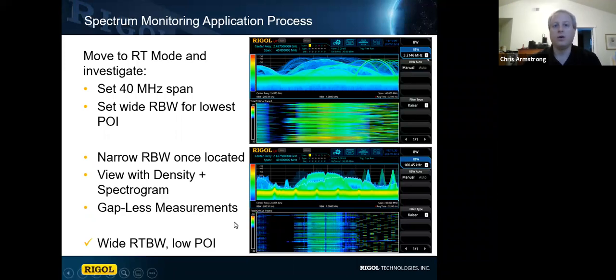Right, so that allows us to decide between accurate power with a wide RBW, or tighten that RBW down for better visualization, but a little less clarity on the actual power levels of those signals. One of the ways that I do this is this RBW2 setting we call gapless, because of the way the analysis tool is overlapping. So I think it's an important concept.